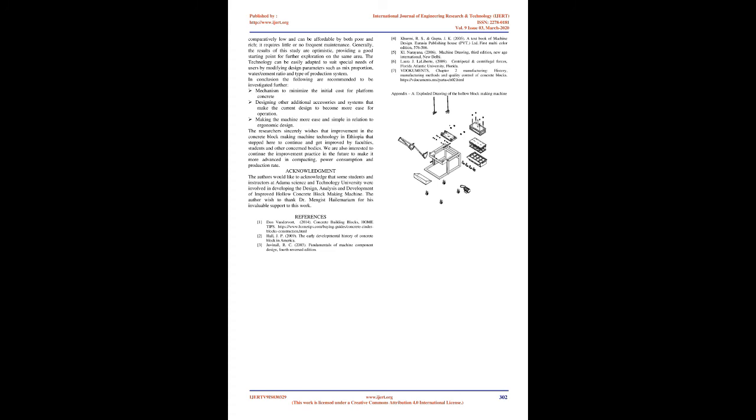V. Key. A key is a piece of mild steel inserted between the shaft and hub or boss of the pulley to connect these together in order to prevent relative motion between them. It is always inserted parallel to the axis of the shaft. Keys are used as temporary fastenings and are subjected to considerable crushing and shearing stresses. The rectangular key is designed as follows.